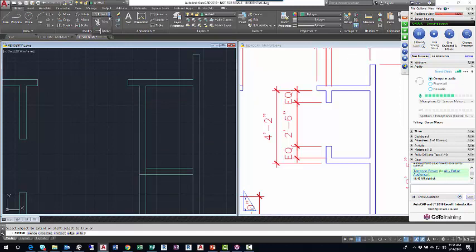Then I'll open up where extend is and I'll click trim. Trim, right click or enter. I'll trim the lines off that are excess, if you will, that are well beyond my closet. Left click this little vertical line inside the horizontals. That hollowed out my walls. Left click the vertical between the horizontals. Now I've got completely hollow walls. Escape. And save.